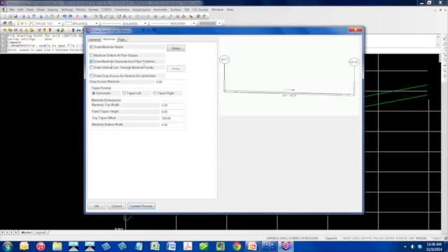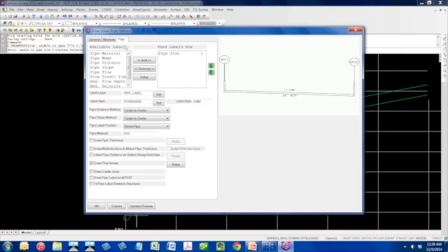Draw manhole separate from pipe polylines. I don't think we're going to see much difference here. Oh yeah, okay. So I did an update preview, and you can see it's going to look a little different. It's showing a manhole top width of 2 and a manhole bottom width of 4, so that's why we have that taper. Maybe that's not what I want. Now, if you've used Carlson hydrology, you can export and you'll get all this stuff anyway without manually having to do it.